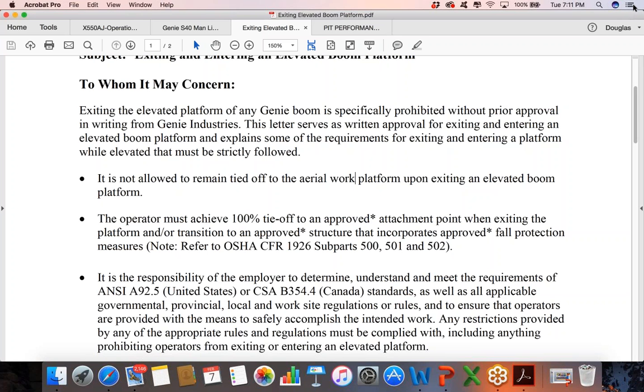It could also be improper ventilation or lack of ventilation, inadequate lighting, high noise, or unsafe storage of flammable liquids or flammable fluids. Also slippery floors, poorly constructed and rigged scaffolding, improperly stacked construction materials, and unmarked low ceilings. And of course, power lines, and unsafe or soft ground conditions. So the hazards go on and on.